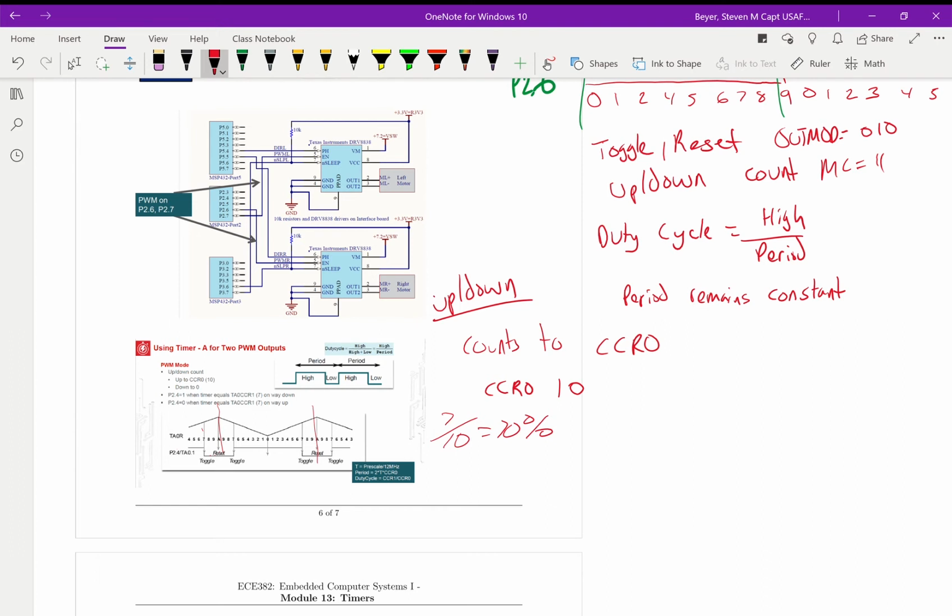So to get our correct duty cycle, what we're doing here is we're using every 2 cycles of this. And that's why we have this 2 right here, because the way this is working, even though we're low for 6 counts here, we're going to be high for 14 here, so we get 14 over 20, which is equal to 7 over 10, or 70%.